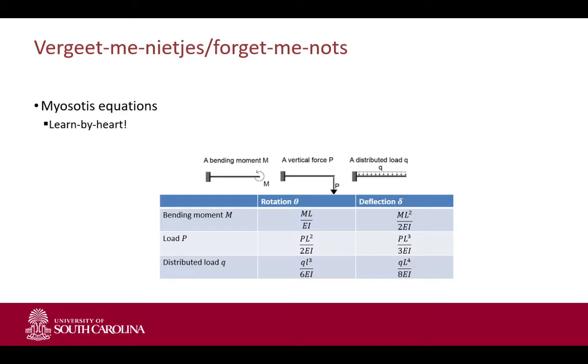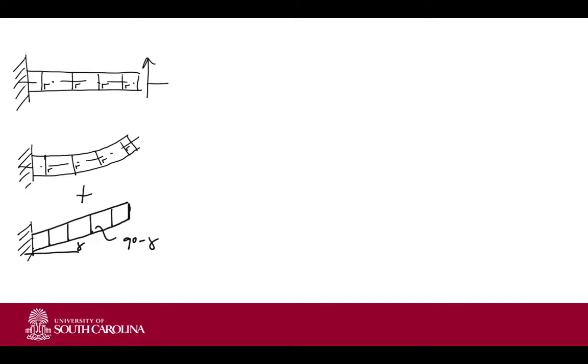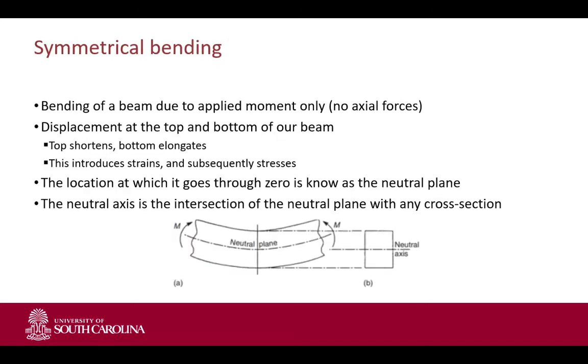And then we did a quick example. So determine deflection based on a force, and we compare it basically with deflections if we incorporate our shear effects, and we derived a ratio of length over thickness, where we could basically say we could ignore it or not. But in this case, we said further that during the bending lecture series, we're going to always assume that we have Euler-Bernoulli. So the main sections, planes remain straight and perpendicular to the neutral plane.